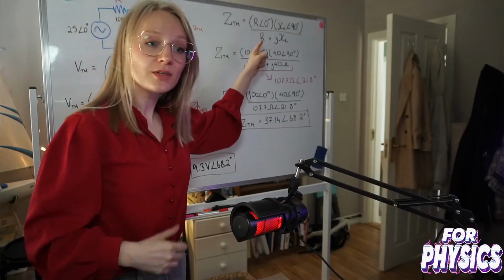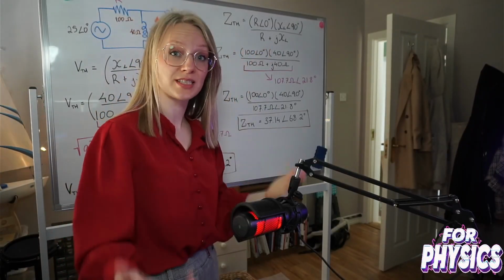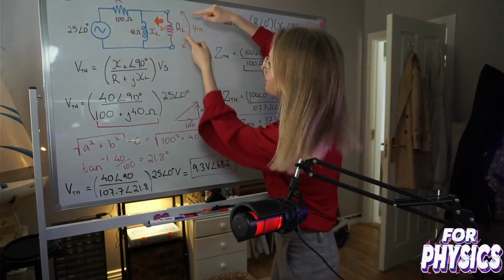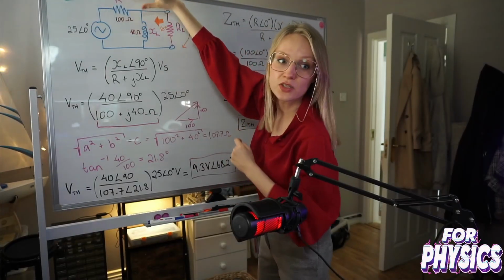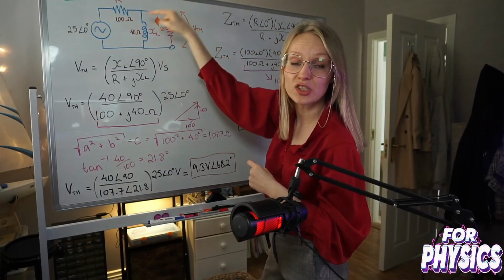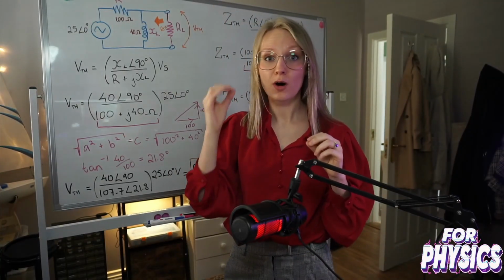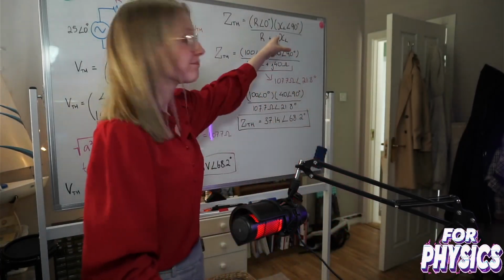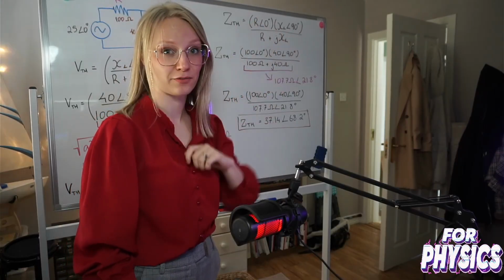Halfway done. We're going to continue with the exact same principle as earlier, but this time we're going to measure the resistance across this load in an AC circuit. So let's look at this circuit. Start here. Oh, our path splits. So basically we have a resistor and an inductor in parallel. Your formula for resistors in parallel, R1 multiplied by R2 over R1 plus R2. Ta-da! It's the exact same thing, but in polar and rectangular form.